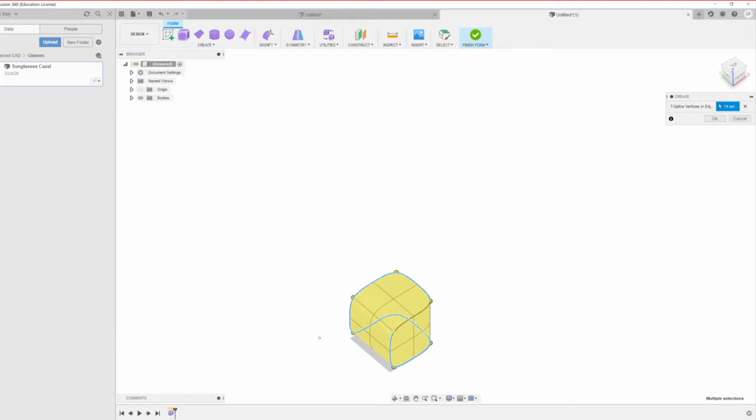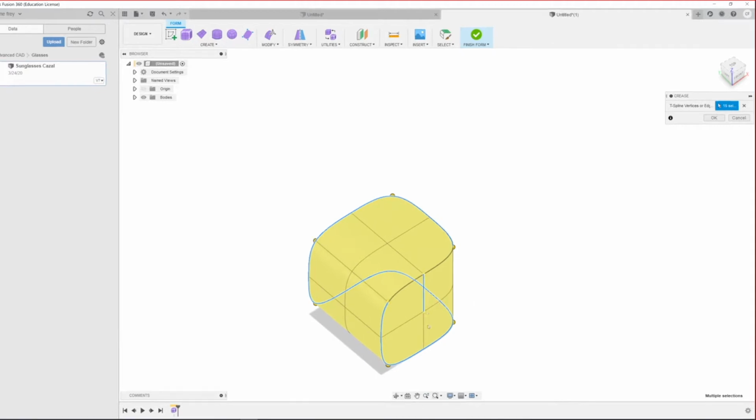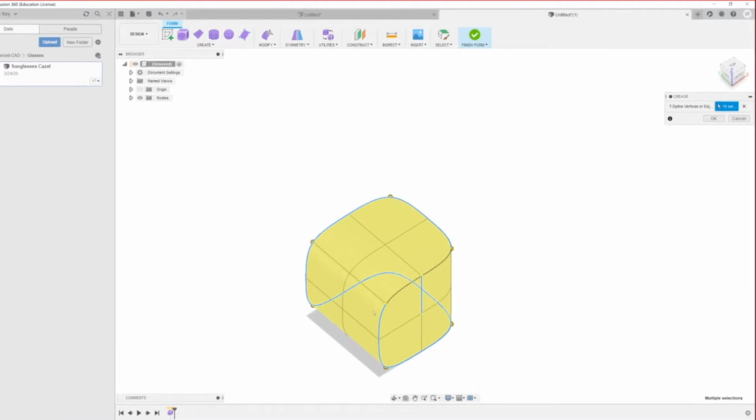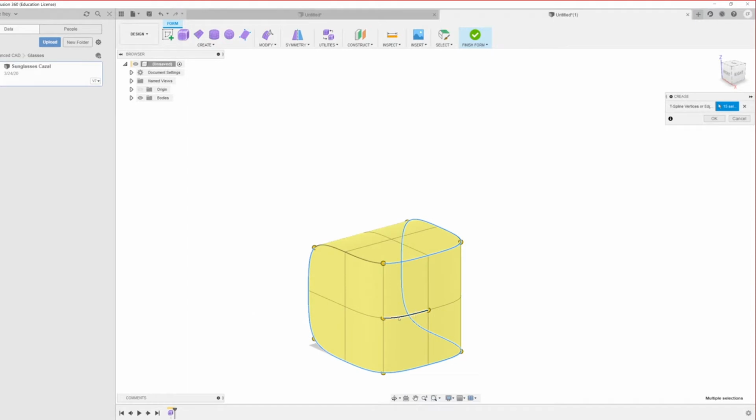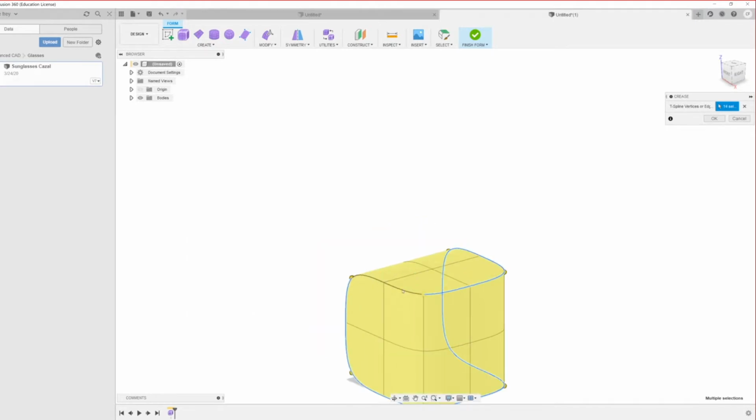Trying to create fillets with the frame form can glitch, or it can become out of control, because there's nothing locking it all in place. Realistically, it's not really locking it into place. So try to generally avoid making fillets like this.